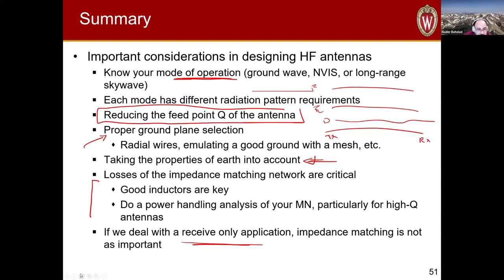So depending on what frequency it is and what takeoff angle I have, let's say that I'm going up and then I'm having my reflection from the F layer. Whenever my waves pass through the D layer, chances are that the critical frequency of the D layer is generally low.